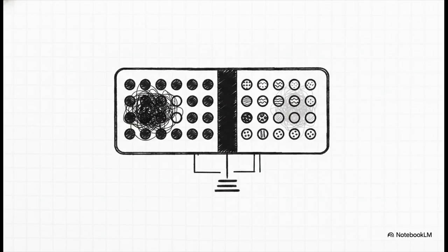Now, this segregation doesn't stop at the cables. It extends right into the connector pinning itself. Pin mapping has a massive, undeniable impact on EMI performance. You've got to group those noisy power pins in one region of the connector and completely isolate your sensitive signal pins on the opposite side. And here's a pro tip. If you have spare pins sitting between them, do not just leave them floating. Grounding them allows those spare pins to act as physical electrical shield barriers right inside the connector body. It's a brilliant little defense mechanism.